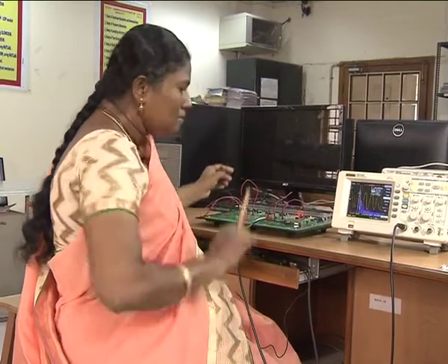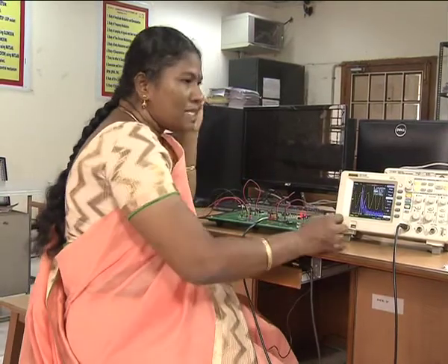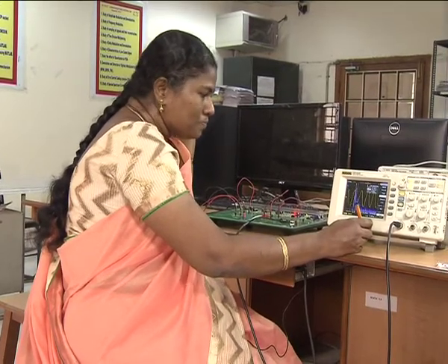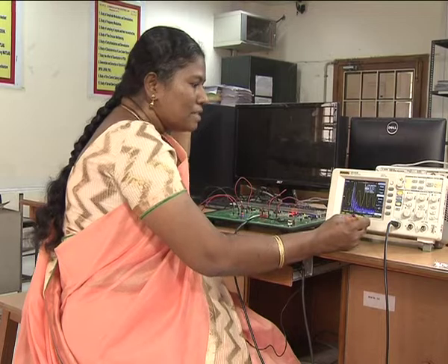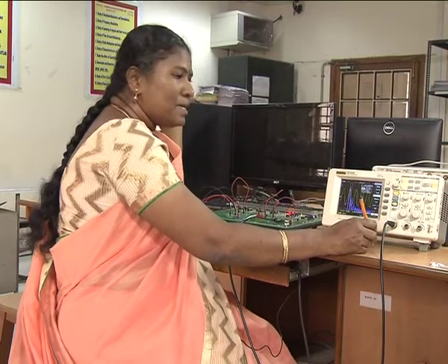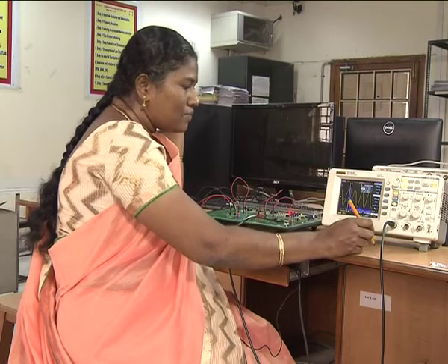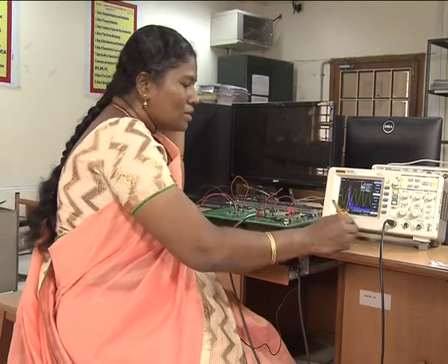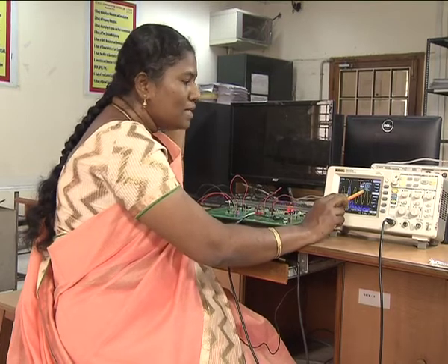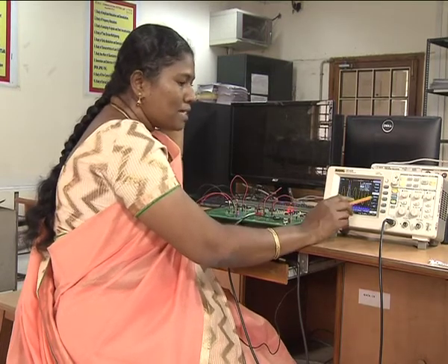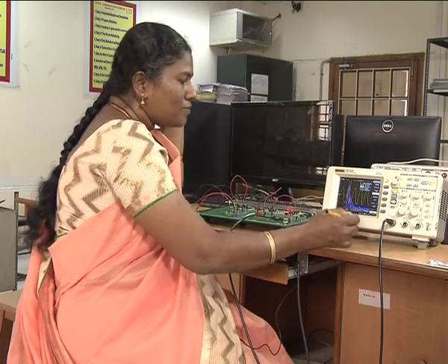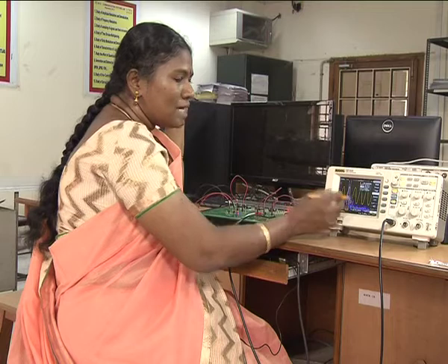Next, for this beta we will be calculating the bandwidth of the signal. Bandwidth BW will be equal to, we have the formula to calculate the bandwidth as 2 into 1 plus beta into Fm. This is the bandwidth required for transmission, according to Carson's rule. For our case, what we got as beta is 38.5. So, 1 plus beta will become 39.5. 2 into Fm will be 10K. So, 39.5 times 10K is the bandwidth required to transmit this signal.